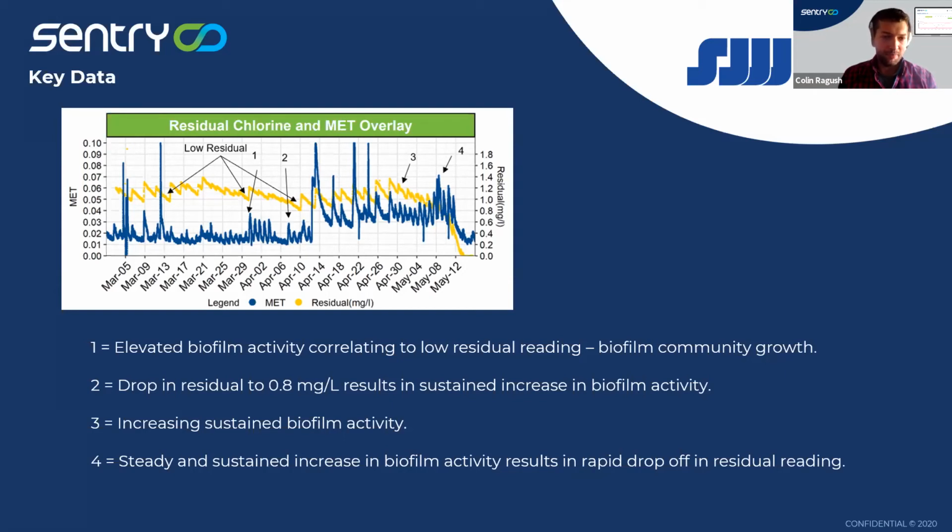And so what I've put on this graph is the chlorine residual, total chlorine residual, and that activity measurement. And we see that the chlorine residual is maintained quite well from March until about mid-April. And we do see some spikes and decreases in residual, but it's a challenge in any distribution system that's large to maintain that residual consistency. And we do see some spikes in activity when these residuals drop, but early on, those are transient. So not a problem because we return to good control conditions.